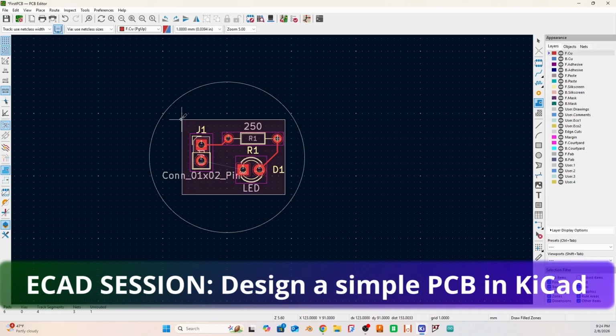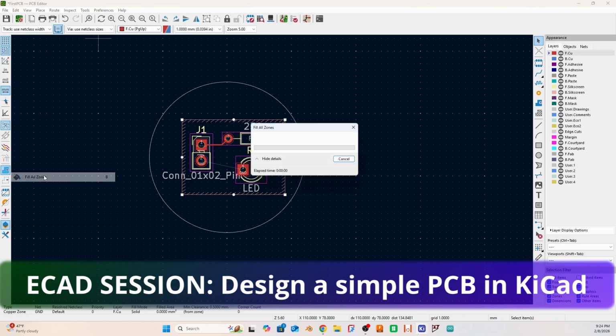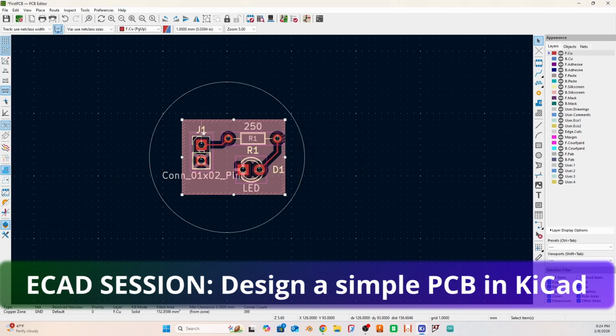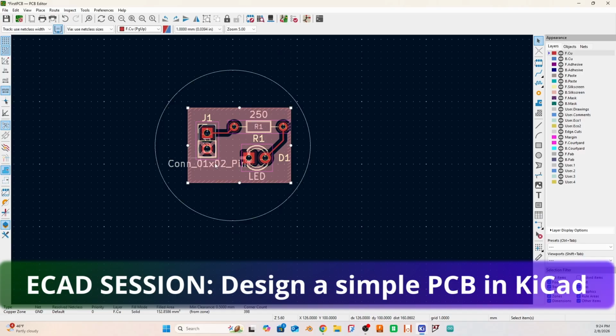About that, then snap in there, and you're good. Now click on B, or come to edit and fill zone with the copper. Okay, there you go, perfect. Now the whole thing is filled up, so all the ground is connected to ground.